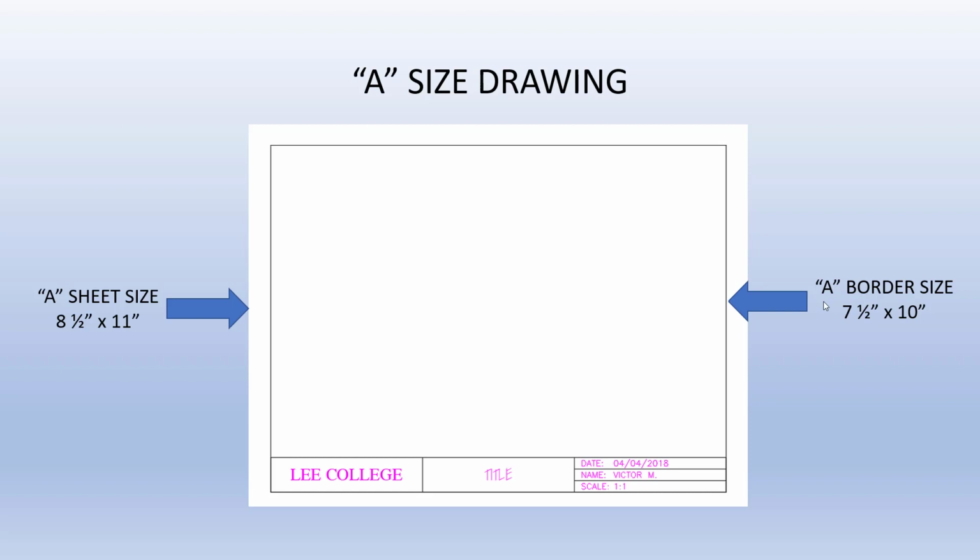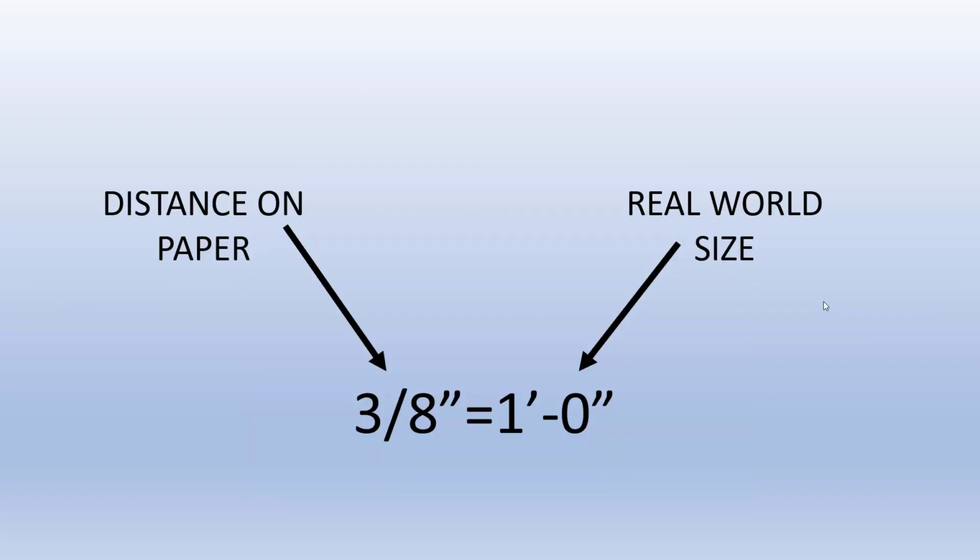You will then scale the inserted border up to the size needed for your drawing using the calculated scale factor, only after you have inserted your border. To help us understand plot scales, let's look at 3/8 inch equal 1 foot as our example.